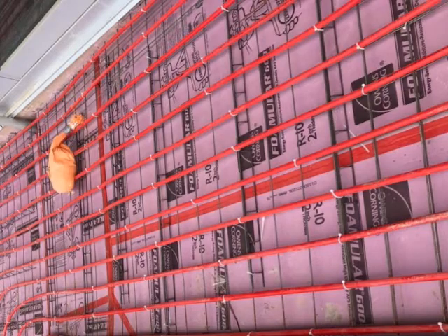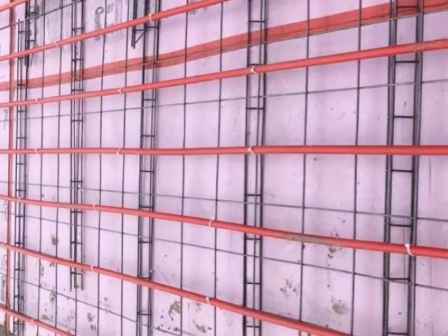If these systems are installed in a slab, you need to have at least a minimum R-5 underneath the entire slab, based on footnote D of table R402.1.2. The key there is with any radiant system, we want to direct where the heat goes. If we don't have insulation on that slab on grade, for instance, where does the heat want to go? Well, it's going to want to heat the dirt because it wants to go to the cold. You want the heat to go up, so that's why you have to insulate on the opposite side of where you want the heat to be on any type of radiant system.